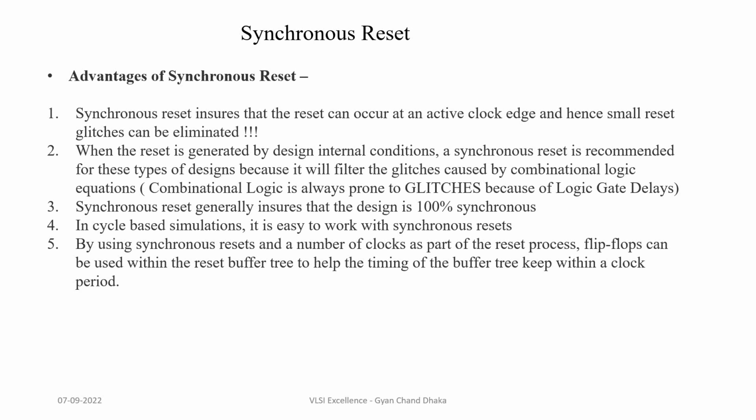Synchronous reset ensures that reset can occur only at an active clock edge, and hence small reset glitches can be eliminated. Suppose you have a reset signal which is something like this in scenario 1, and in another scenario the reset is something like this.